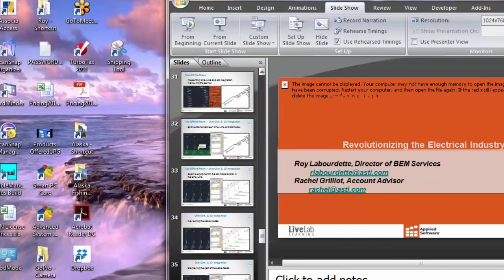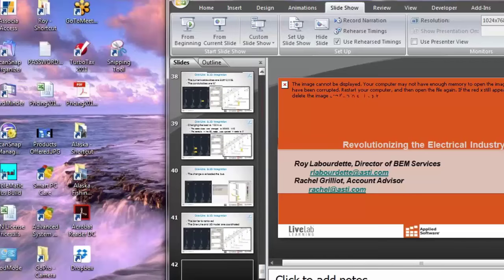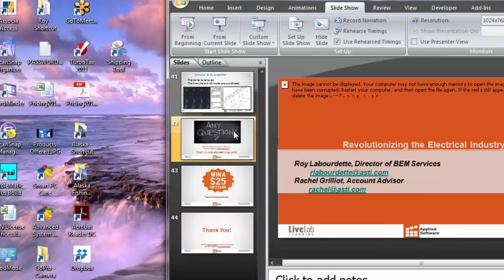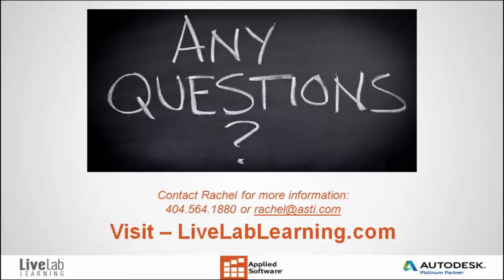Of course, I'm going to XREF in some backgrounds, whichever backgrounds are most convenient, so that I can get enough information to do my preliminary routing. But the heavy lifting is going to be done in Navisworks, where I can get a lot more information visually into the program, and I can also use the Clash functionality in Navisworks to clear all those interferences.